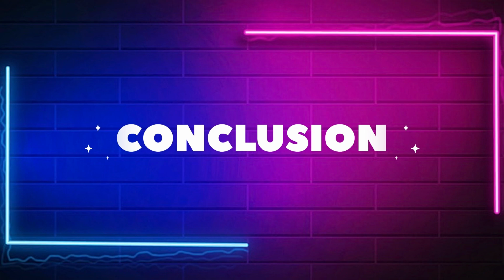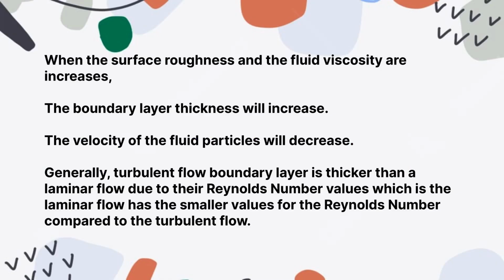Next, we look at the conclusion for this experiment. When the surface roughness and the fluid viscosity are increased, the boundary layer thickness will increase, but the velocity of the fluid particles will decrease. Generally, a turbulent flow boundary layer is thicker than a laminar one due to their Reynolds number values, as the laminar flow has smaller Reynolds number values compared to the turbulent flow. Thus, all the objectives have been achieved.